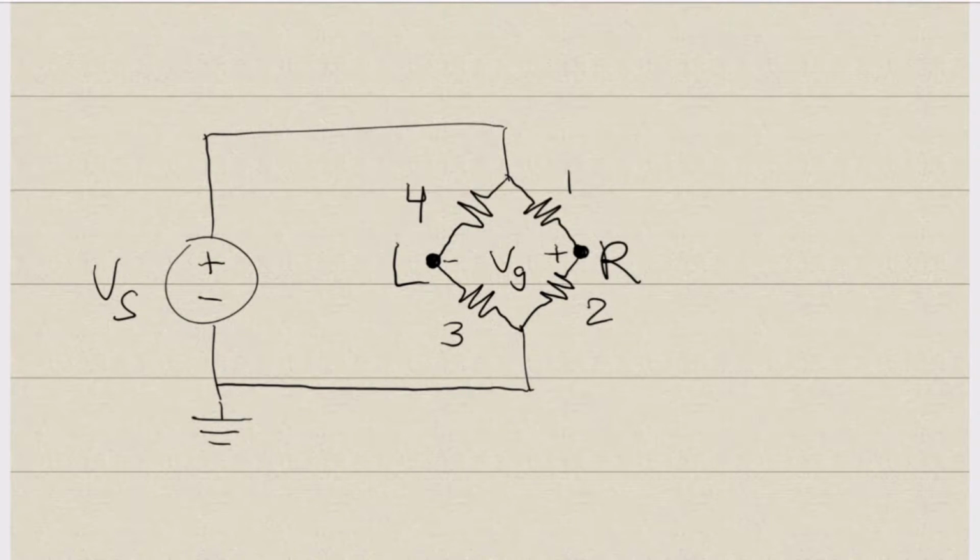The voltage across these nodes may be measured, and then if the values of some of the resistors are known, we may calculate the resistance in the unknown resistors. We will call the voltage between the right node and the left node Vg.